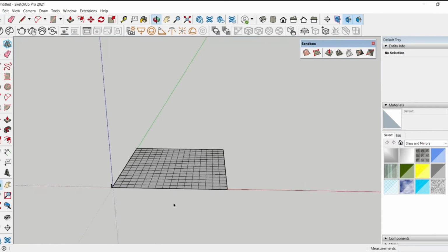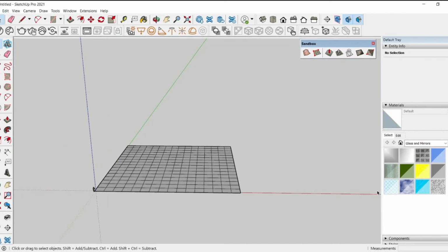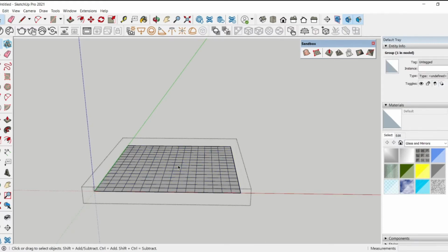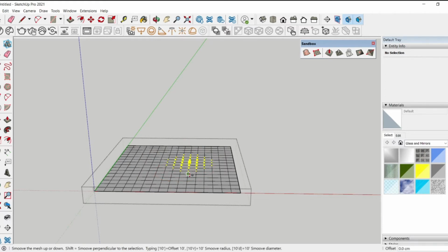Let's look at the third tool, Smooth, which I will apply exactly in this grid. With this tool, you can model the entire surface. I click on the grid and then on Smooth, and you see that I get a red circle that covers the radius of the surface. In this case, I click at one of the points on the surface and lift or push down.